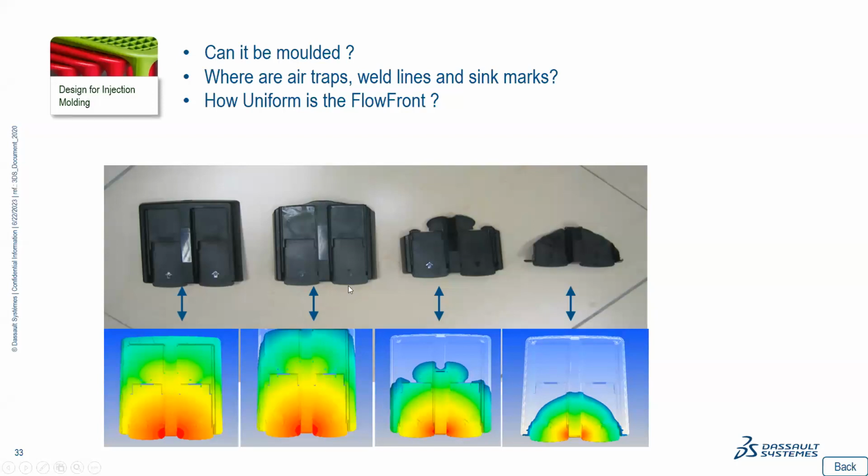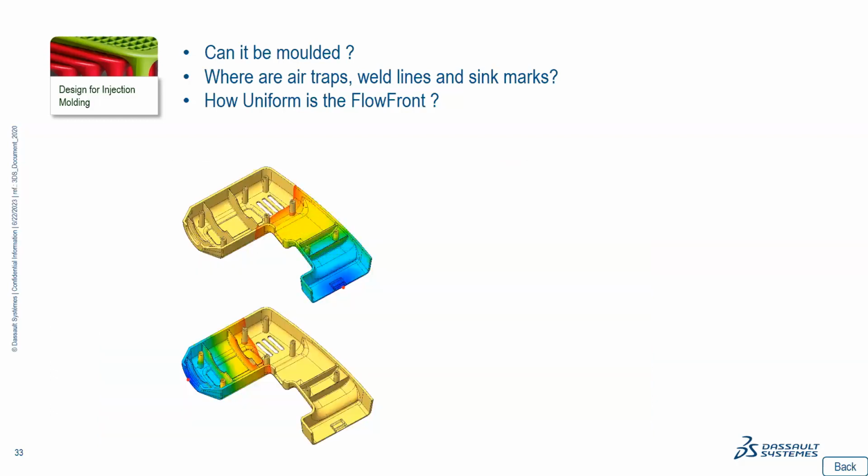And what is very important when you're doing plastic, for example, is first of all, can you inject this plastic part? Sometimes you can have an issue because you will start injecting your plastic part and it will stop, because the pressure is too high to inject this plastic part, or it cools down too fast. So the plastic during the injection solidifies and then it stops. It's what we call a stop, in the plastic. Then what you can also want to see is how the flow will evolve, what we call the flow front.